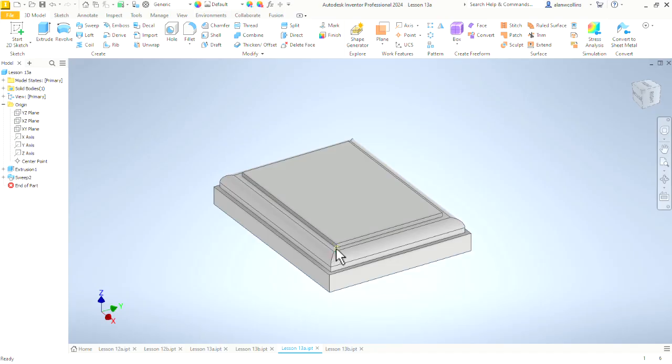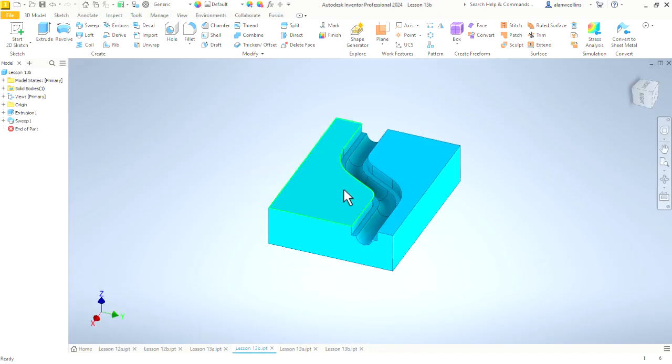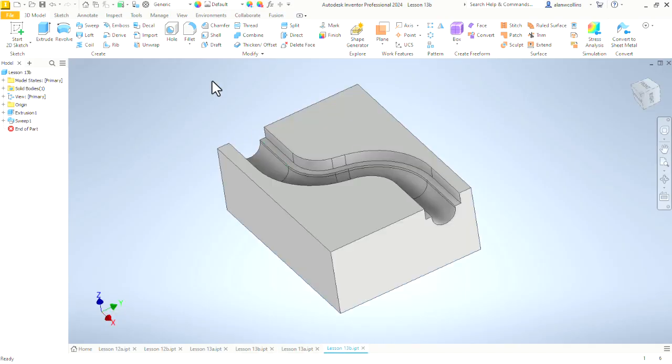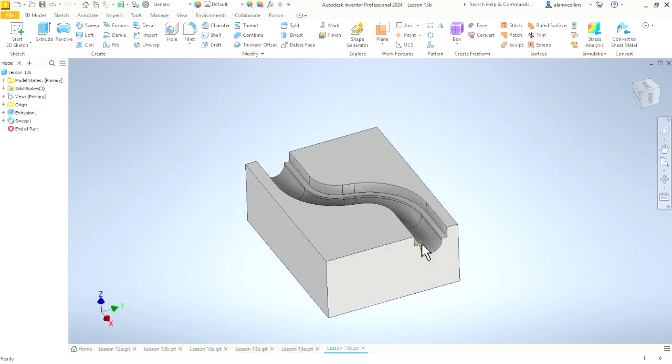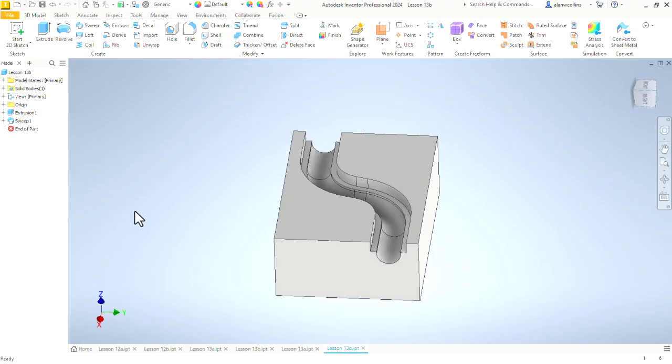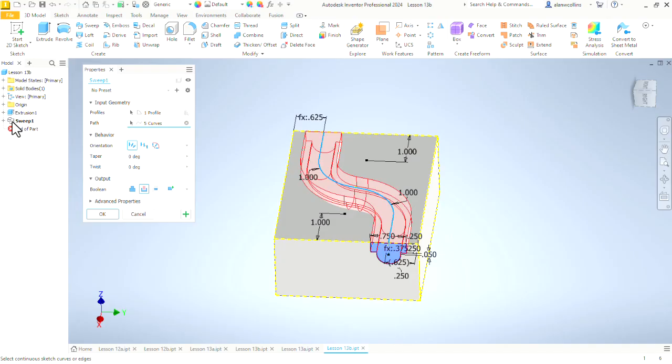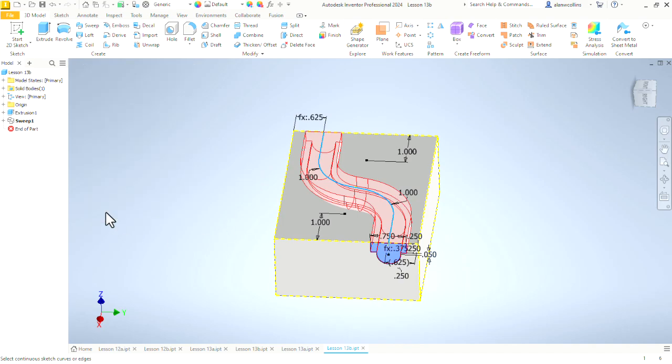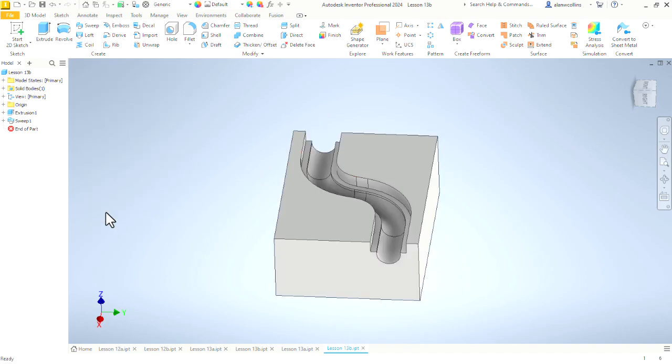The one that we just created, the second attempt at it, we made squared off corners. Or we can have, there was our example, there's the one we just did. You can create a profile and cut it along the path that you create. That's the basics of the simplest use of the sweep command. There's some other options and other things to look at in here at some point. We'll take a deep dive into all those. But for now, that's enough to get you started with sweep. So go practice that, draw some different shapes, work with the numbers, get a feel for it, and then come back for lesson 14.